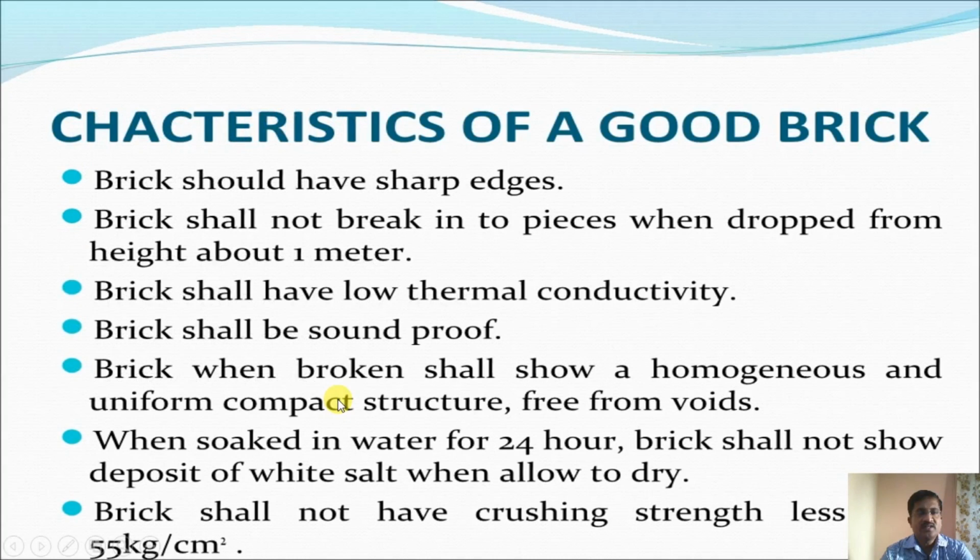What are the characteristics of a good brick? Brick should have sharp edges. Brick shall not break into pieces when dropped from a height of 1 meter. Brick shall have low thermal conductivity.